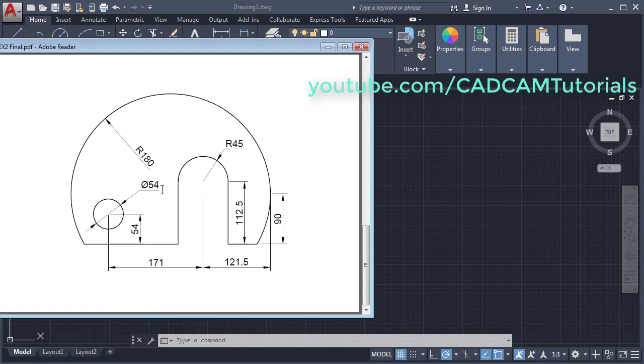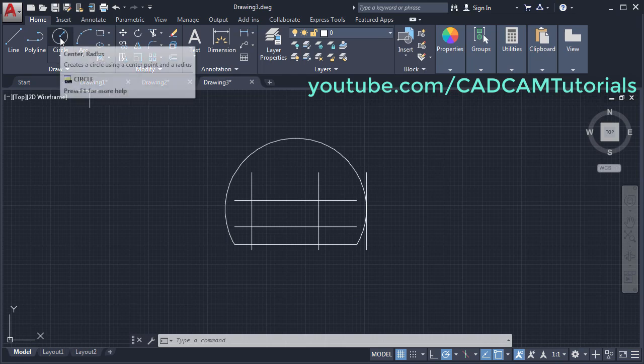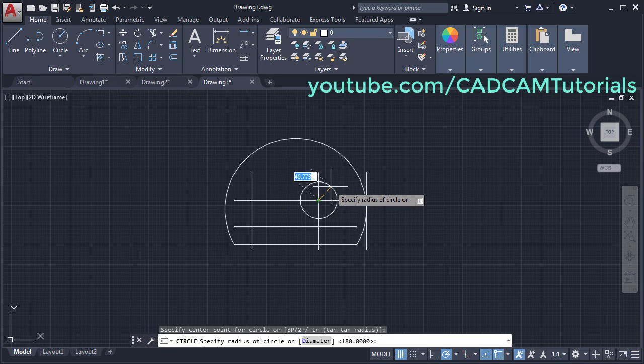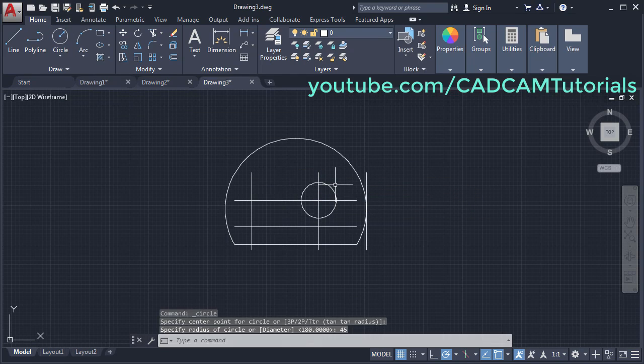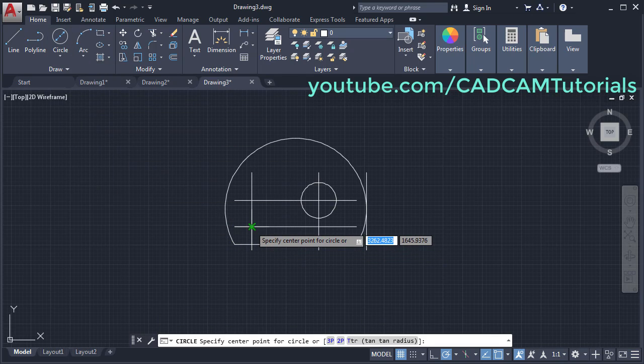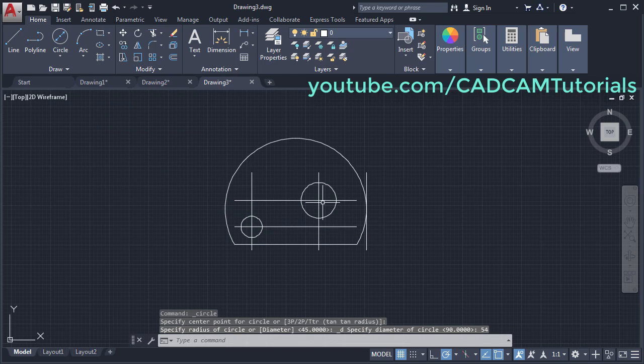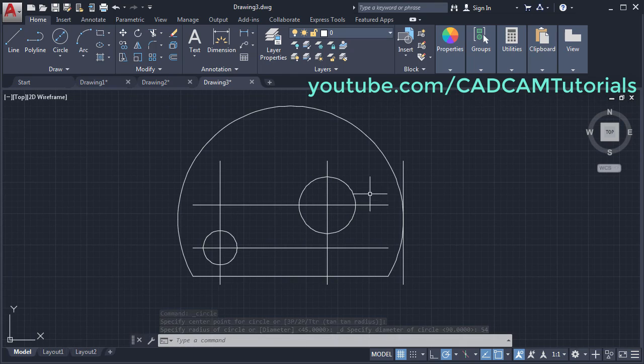Then create the circles of 54 diameter and 45 radius. Click on circle, give the center point, give the radius of 45, enter. Then click on this arrow, click on center diameter, give the center point, give the diameter of 54, enter. Then zoom it. We want two vertical lines.